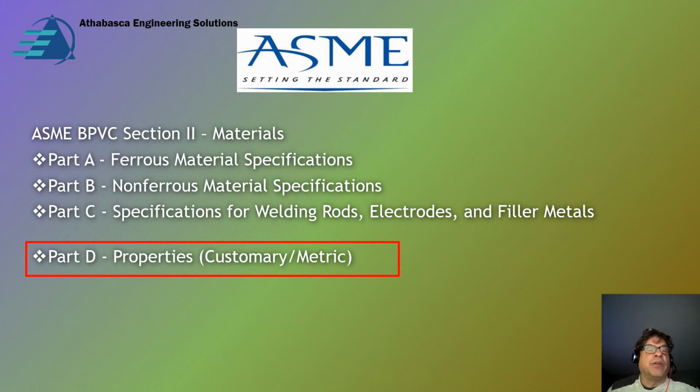The ones that are appropriate for use for pressure vessels have to meet the SA-516 requirements. So a pressure vessel fabricator with an ASME certificate can upgrade A516 plate by an inspection of their choice, and they can do the inspection, and then it becomes SA-516 Grade 70 plate. So basically, that's the difference. When you read Parts A and B, those specifications are almost identical to the ASTM. There are differences, and you have to be careful.